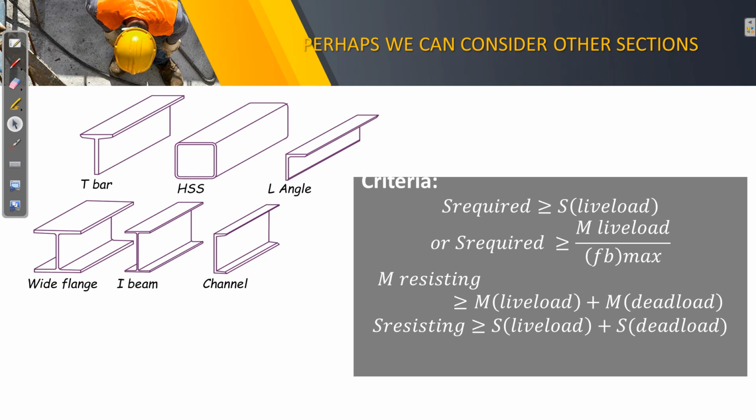Okay, so if we cross multiply this one, it will yield the same formula that we have been using, that the flexural stress is equal to Mc over I, and further it will be simplified to M over S or M over Z. Okay, so if we cross multiply this, it will just interchange,